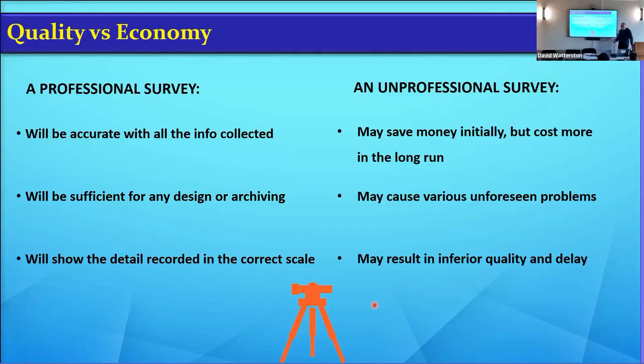And then some companies will say, I'll do the survey for a couple of £300. You know, a third of ours, half of ours. But they will use either a drone, or they'll go in there with the GPS, a second-hand one, and only do it once. Or the drone will go over, take a load of photographs, make the maps, but it hasn't got any ground control. So it doesn't know the true distance from A to B.